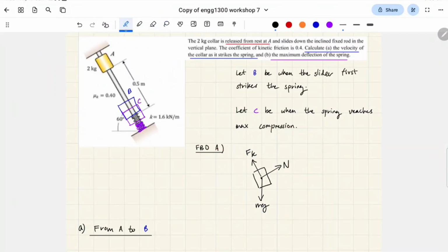So, as per what we were talking about last lesson, you want to think about where you're taking the sum of the forces. Because if you take the sum of the forces in the vertical direction here, for example, you're going to run into problems. You're going to run into these two unknowns, right? The good news about friction and normal force is they're always perpendicular to each other, right? And so that means that we can always split it up like this.